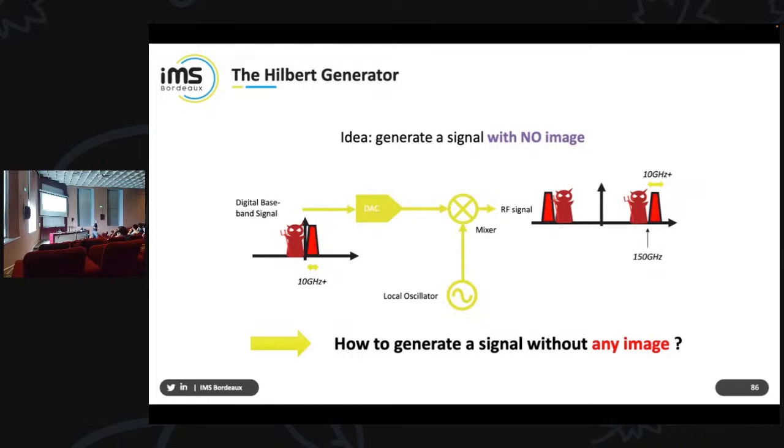I'm just wondering, the image frequency you're talking about, is that the same thing as aliasing? Same thing as aliasing, yes. Aliasing, another word in French, but it makes some replica in the spectrum. It's exactly the same. It comes from the negative frequency, and we can't see it. We can't see negative frequency. So why not we kill it when it's born? If we do that, boom, it will disappear, of course, and that's it.